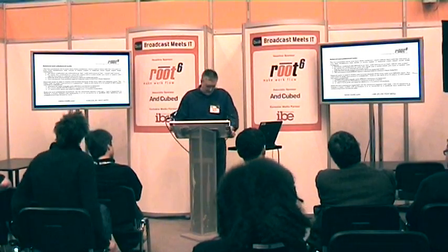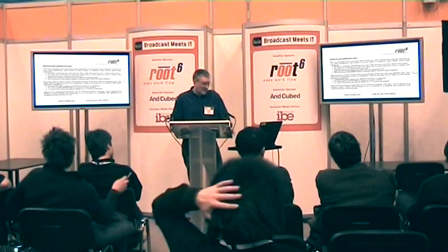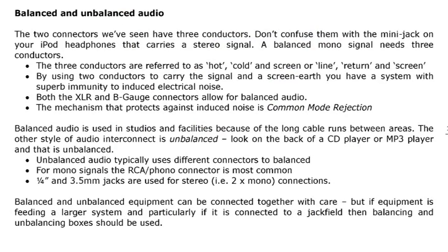The other thing that's important to know about in pro audio is balanced and unbalanced. Something that confuses a lot of people, but kind of shouldn't, because it's not that hard. If you look on the back of your domestic DVD player, you'll see a couple of RCA connectors or phono connectors. The audio out the back of your DVD player is an unbalanced signal. It just has 2 connections to carry the left and 2 connections to carry the right.